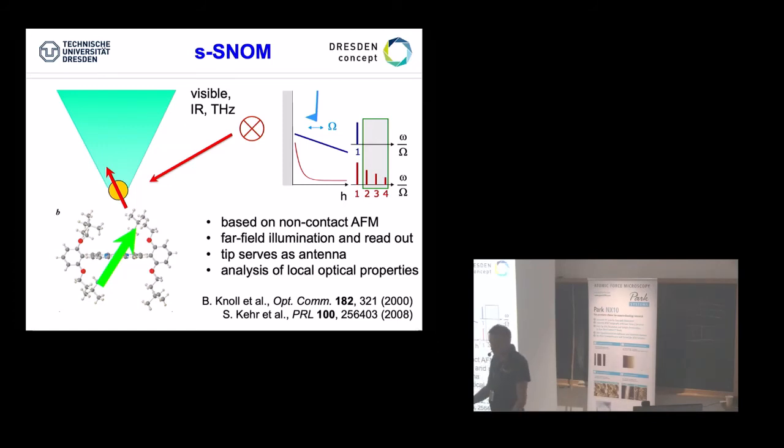So that's basic physics. We're inducing a dipole in the tip, and then actually we're inducing it into the sample. These two start to talk to each other like in a dipole interaction, like we know from magnetism, like we know from van der Waals forces. And hence, we see that these dipole forces again are a nonlinear interaction as a function of distance. This is again good, because we can now apply the whole mimic just shown before. That means we can really measure the nonlinearities at higher frequencies simply by using a standard scanning force microscope.